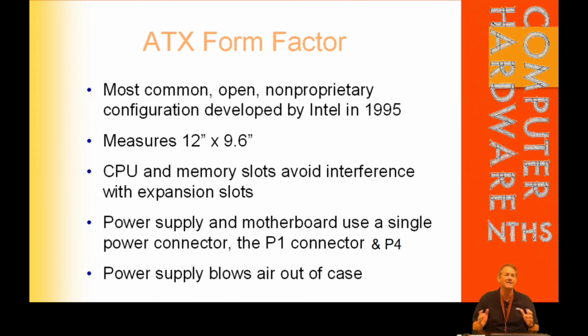It's been around since 1995. That doesn't mean it's old. It means that it is the basic form factor that we've been working with for a long time. That measurement, 12 inches by 9.6, is very fluid. You'll see that as we look at some of these other slides as we talk about form factor. We talked previously about how the CPU and the memory slots are positioned on an ATX form factor in order to not interfere with the expansion slots.